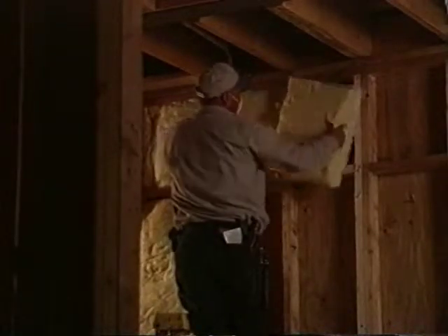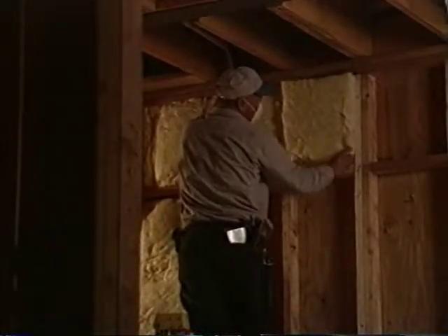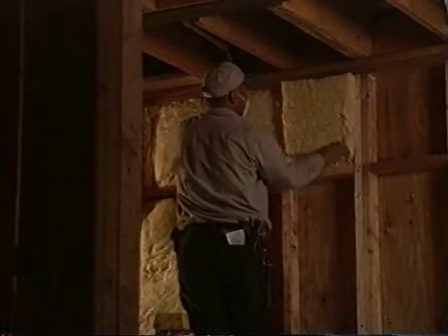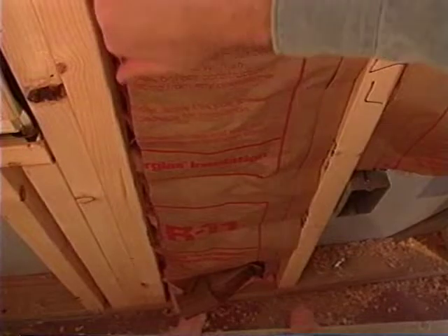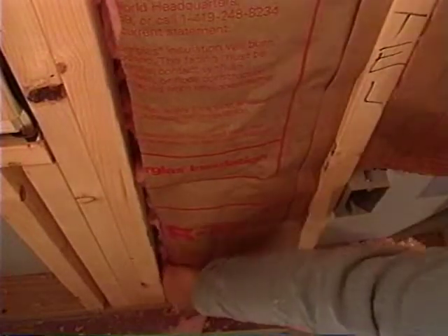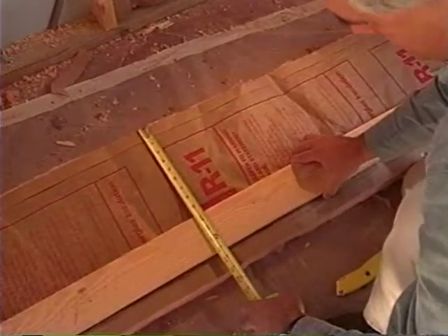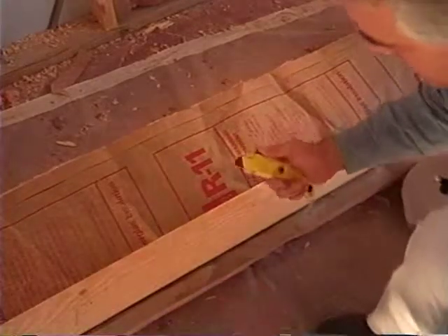As we've heard, a good insulation job is continuous. That is, there are no gaps in the thermal boundary. Gaps commonly occur when batts are cut too short and leave a hole at the top of the stud cavity or at the bottom. Gaps can also occur when batts are cut too narrow to fit the stud cavity. The best rule of thumb is to measure the area you plan to insulate before you cut to ensure a tight, sure fit.